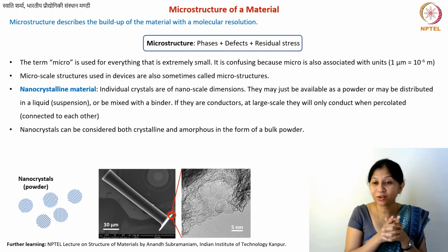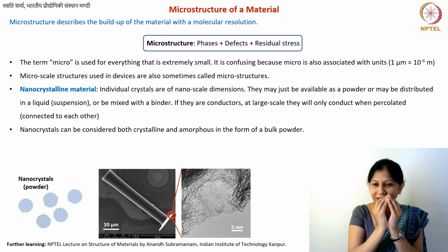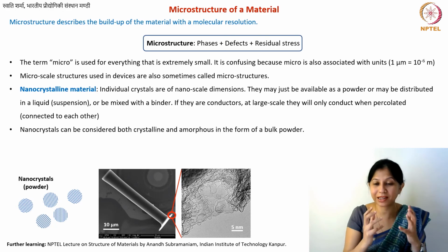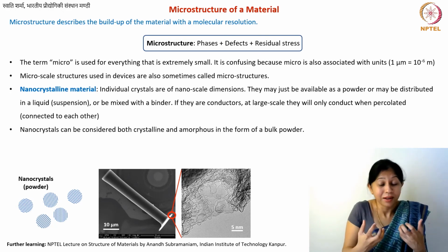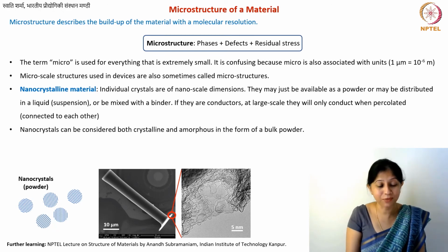But with nanocrystals, the defects will anneal out. The defects will leave the material. The entire crystal is so small. Where will the defect be? If there are defects, this makes it a very high energy structure. It will try to minimize its energy and get rid of the defects. So many properties of the materials change at the nanoscale, and that's why they're very interesting materials.